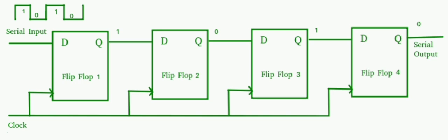Now ROM, the read-only memory, is also called mask ROM. The information is inscribed in the form of presence or absence of a link. PROM, the programmable read-only memory. PROMs are ROMs which are field programmable but lack erase capability.